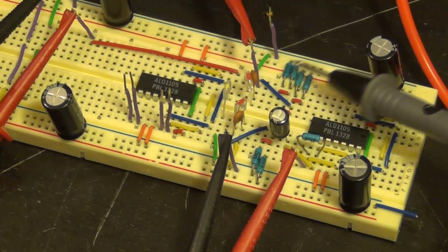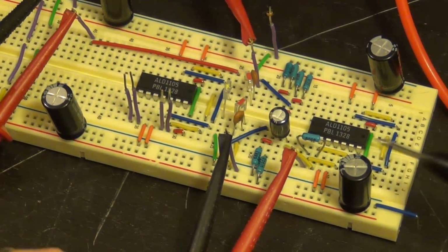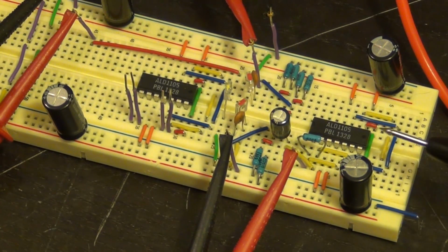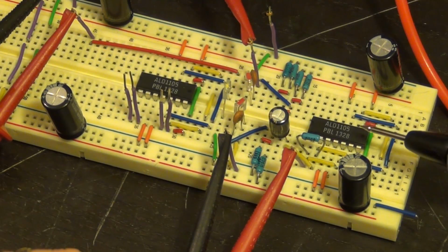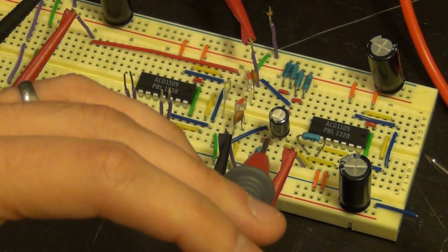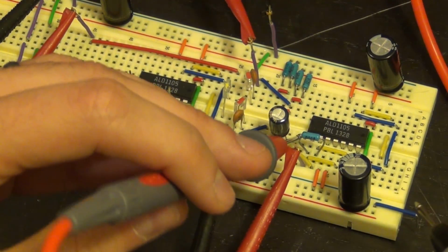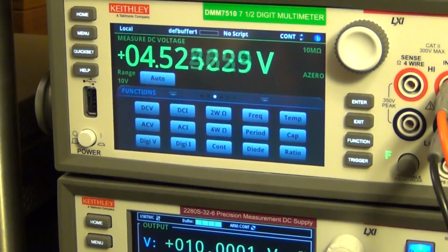One of them is just a resistor that's up here, and then using this chip we've built the transimpedance amplifier using the NMOS and PMOS transistors, and we also have this RF resistor in feedback. Now the first important thing to check is to make sure that this is biased correctly. As we said, the RF resistor is also going to bias this itself, self-bias. So we can look at the output voltage and make sure that it's where it should be, and we can see that it's at 4.5 volts, which is where we expect.